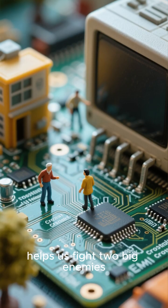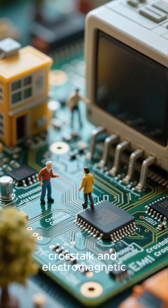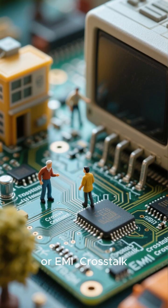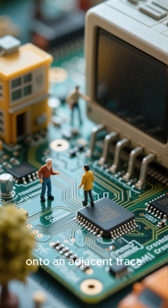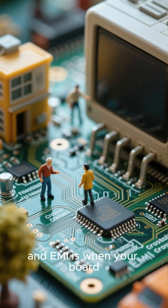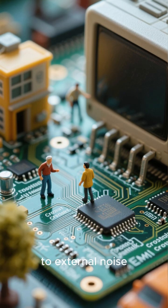All of this work helps us fight two big enemies: crosstalk and electromagnetic interference, or EMI. Crosstalk is when a signal on one trace couples onto an adjacent trace, and EMI is when your board radiates noise or is susceptible to external noise.